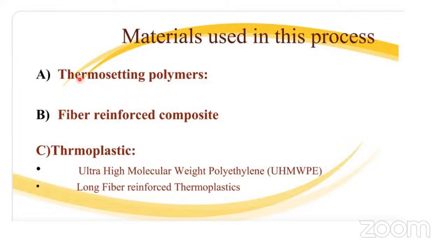Now, what is meant by C stage resin in a thermosetting polymer? C stage resin is nothing but whatever you are getting in the B stage, resin plus all additives. You are mixing that, making a powder of all these ingredients, and with resin mixing that, compounding we do. After compounding, you are molding on compression molding press, transfer molding press, and after molding, that article you are getting, that article is called as a C stage resin.